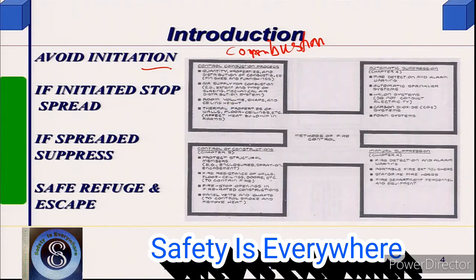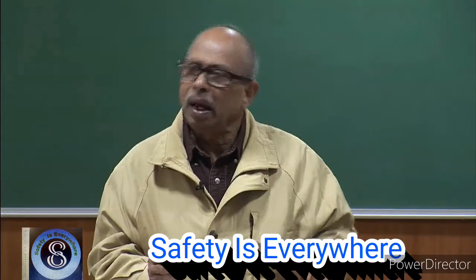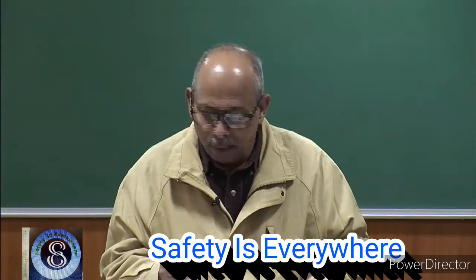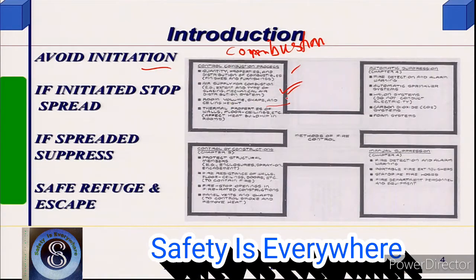This depends upon what we will go into in detail, but just as an outline: the quantity of combustible material within the space. Then air supply, because as you shall see in the next slide, three things are essentially required for fire. One is the fuel, the other is air, and it has to initiate, therefore you need heat. After that it sustains on its own. So air supply comes from ventilation into the building, and the combustible material present provides the fuel. And then it also depends upon the space, the volume of the room, etc.